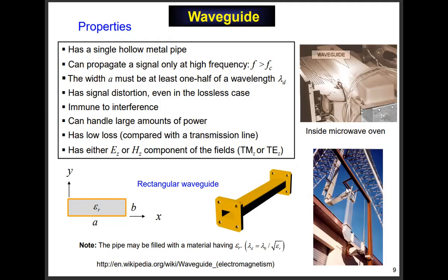Here's an example of what you might call waveguide plumbing, where rectangular waveguide is being used to go around like this. And this is coming from some building, probably some kind of transmit, a relay station or something. So there's some building in here that's amplifying a signal probably. I'm just guessing, I don't know, but then the high power signal after being amplified is being pumped back into a transmitting antenna here on this tower. It's probably what it is, but I'm not 100% sure. Okay. Now, waveguides are used in almost all high power radar applications. I mean, radar is where you really need a huge high power signal. And so, because the wave has to come from the radar antenna, hit the aircraft or whatever, and bounce all the way back, right?